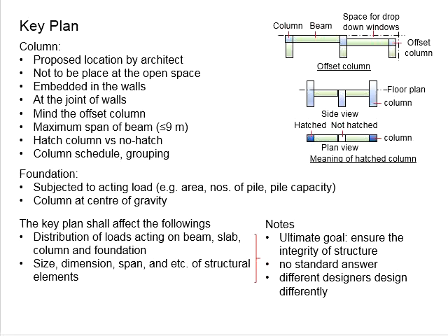Let's say now you have a combined footing. You need to be mindful of the centers of the loads. Combined foundations mean your foundation is now taking the loads from more than one column, because the columns are placed quite near to each other, and if you use pad footings, they may clash into each other.